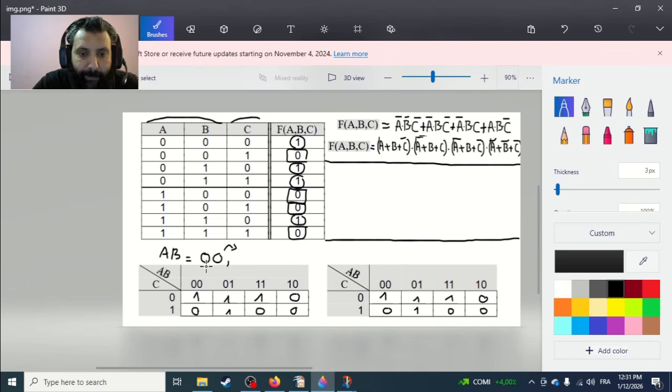For instance, if I pass from this one to the next, I could write 0,1. 1,0 is valid too. Anyway, you can't use 1,1, because here I changed two variables. This is not allowed in Gray code. We will take the first possibility, 0,1.